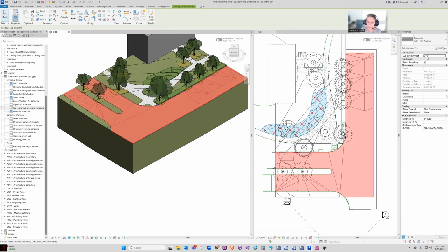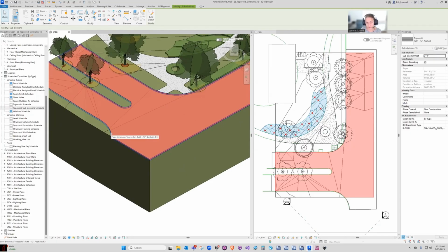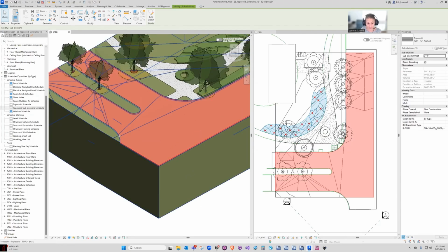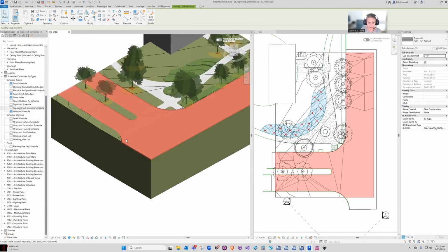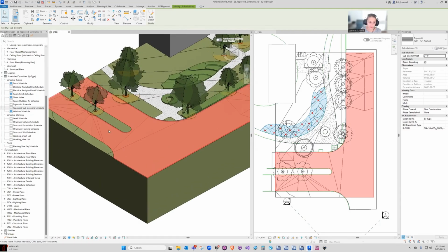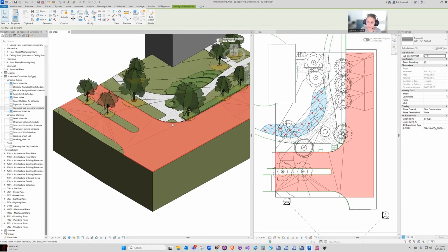Now when you make a new subdivision, the default height or offset is always going to be 0. This is the other big change. We have subdivision types and we have recessed subdivisions, with 0 being our new default. I think, particularly in early concept, if you have architects using subdivisions, this is how they are going to want to use them. This is the way the old subregions worked, in that they were always hosted in plane with your base topo. So that is how that works.